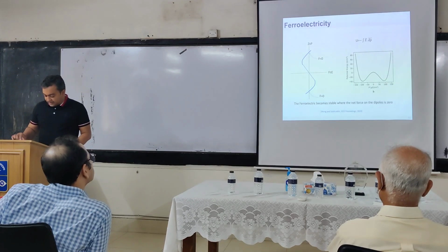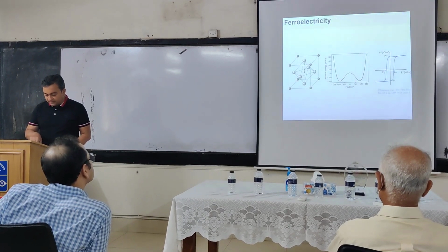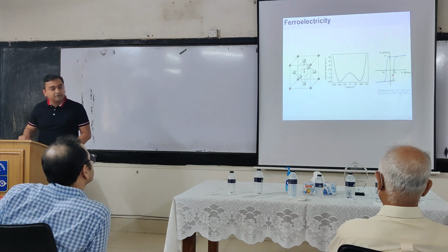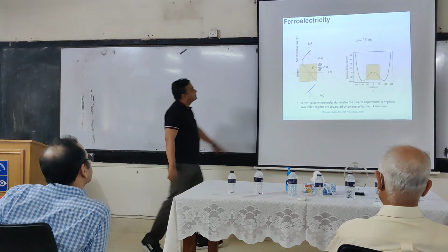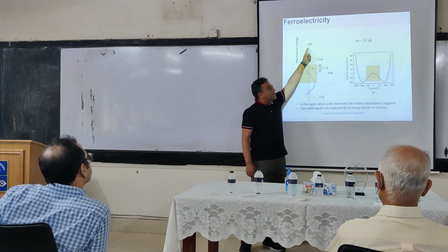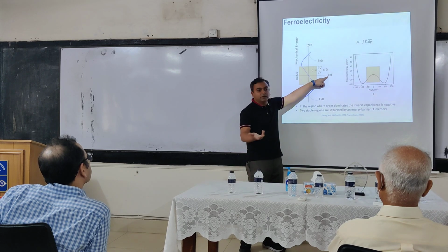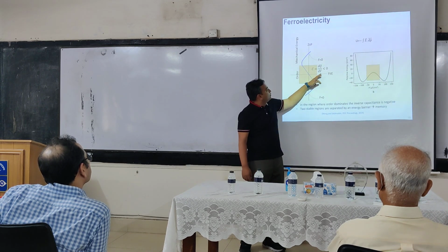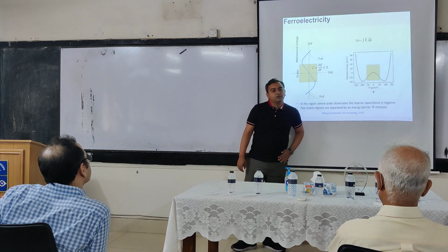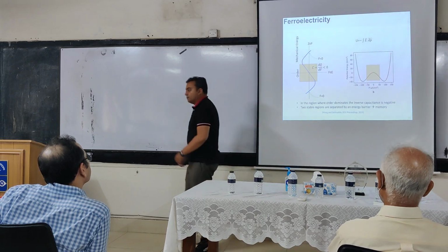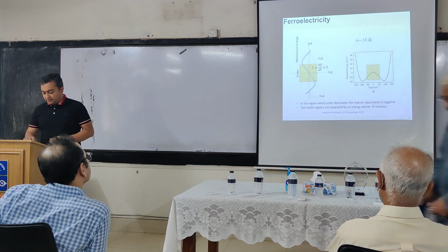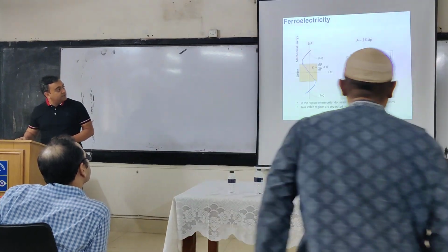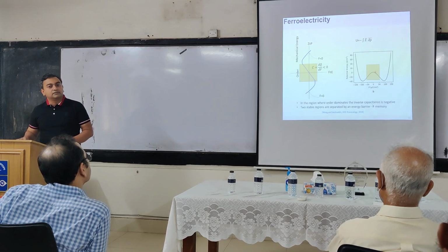But now that we know this, we have an atomistic theory as to why a ferroelectric material will give me this energy landscape and this hysteresis. At the same time, it tells me that right here, polarization is charge, electric field is equivalent to voltage. So dP over dV is less than 0, which means right here I have a region where the capacitance is negative. Similarly, if I compare that with the energy landscape here, this is the region where capacitance is negative.